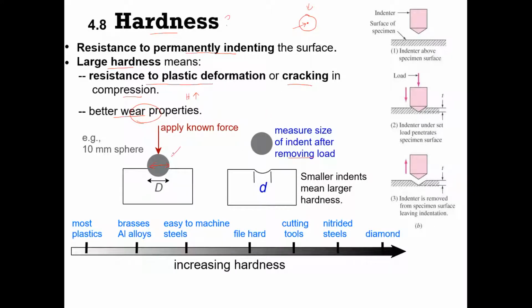Basically we have two types of indenter: a sphere type, and a diamond shape. Let us look at them one by one, and how they measure the hardness of the material. This is the sphere shape, normally for steel or tungsten carbide material. Here is the diameter of this sphere, and we apply loading.